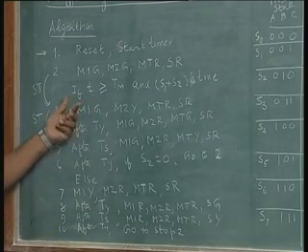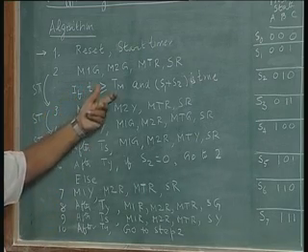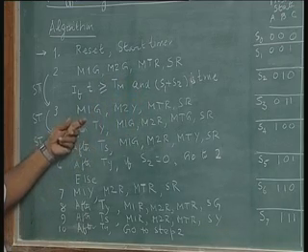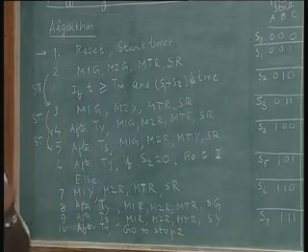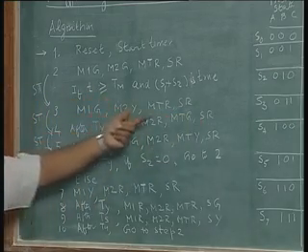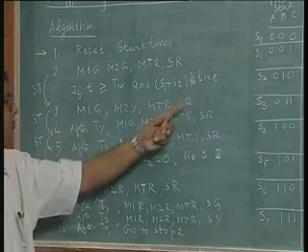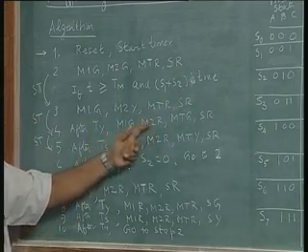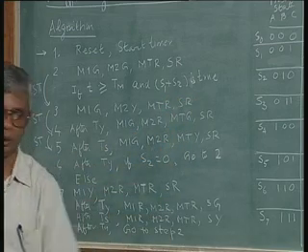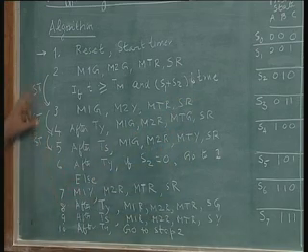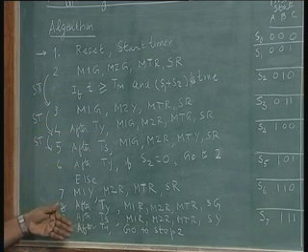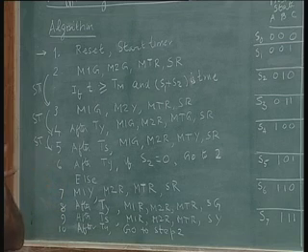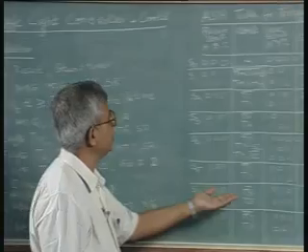So, what I should really say, if t is greater than Tm and S1 is true, start timer and go to M1G, like that I should say. Similarly, I say M1G, M2Y, MTR, SR, and after Ty, etc., start timer. So, start timer should be put in each stage, as I did put here. So, that is assumed. This is just to recapitulate the ASM, because it looks a little complex. And now with this background, I want you to look at the table. This is the ASM table.